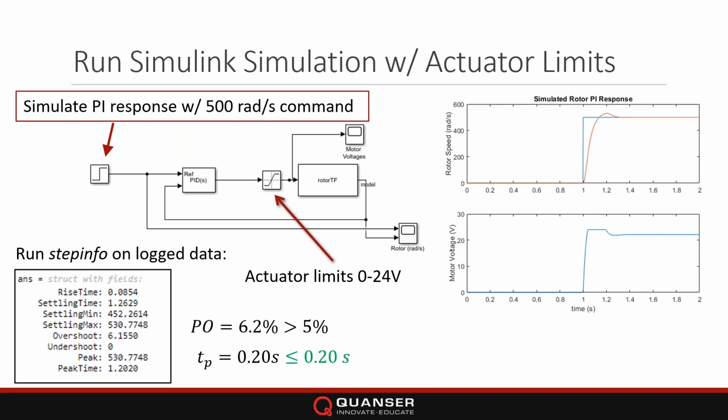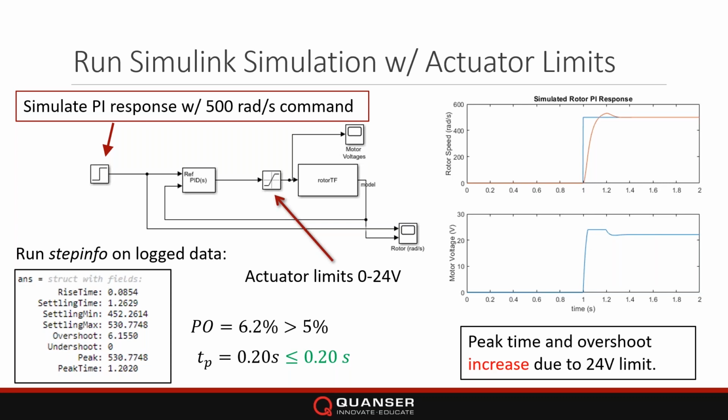So happy with the peak time. Overshoot is a little bit more than I wanted. I had my mindset at a 5% overshoot. However, given that this is just the first portion, I want to see how this will affect the ultimate goal, which is controlling the pitch, right? Because we still have a couple of steps in the control design process. And this can be iterative. I know I can always go back to my design, and if necessary, I can tune this to get a better response. But so this is okay. We can now move on to the second portion and how this lines up.